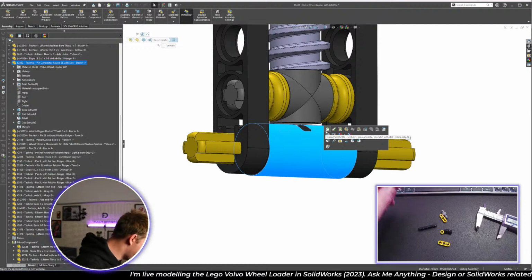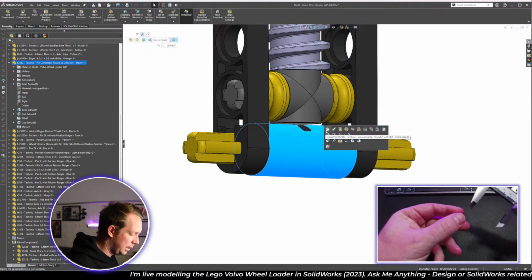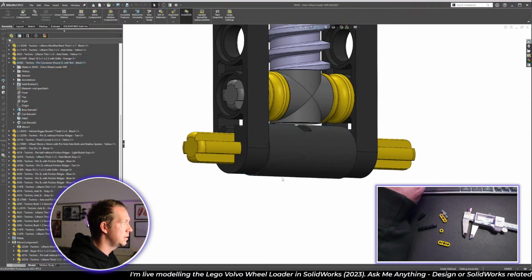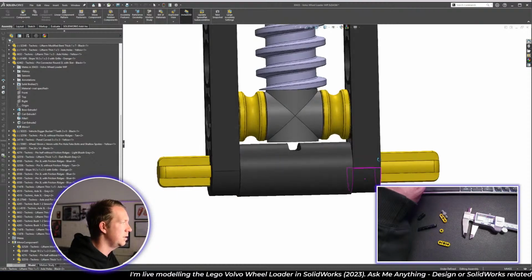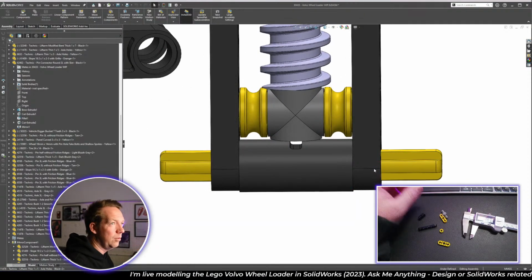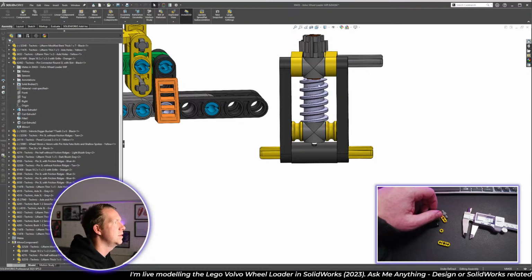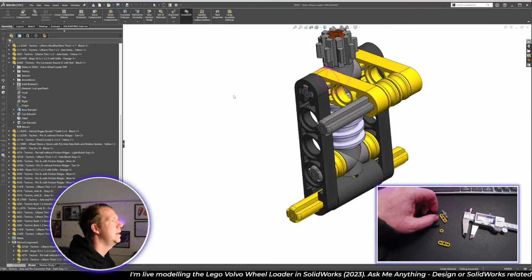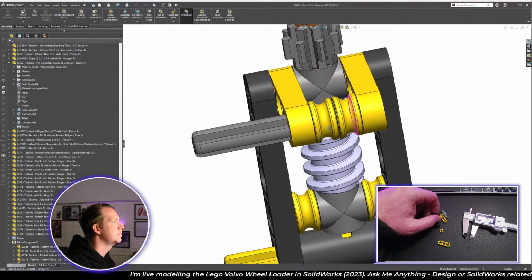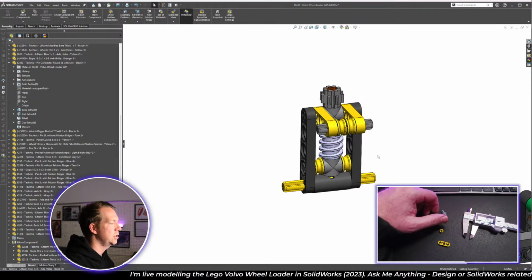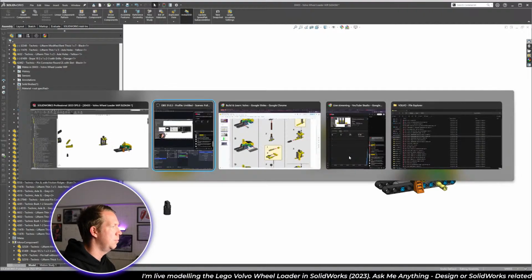And this black one, I have that as 7.8mm. That's correct. All right, so there's a little bit of difference in size. And that would be the next step of this project. Like, as you assemble things, you can see how they fit. So you can see where there's clearances or interferences and how accurate you are, and you can make adjustments to your model. That all looks good now. We'll do an interference detection later. Let's keep going and put more of it together.